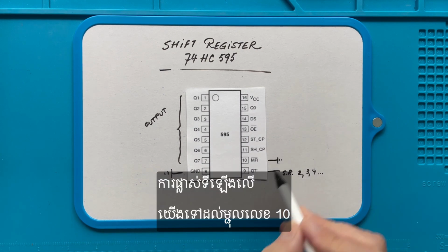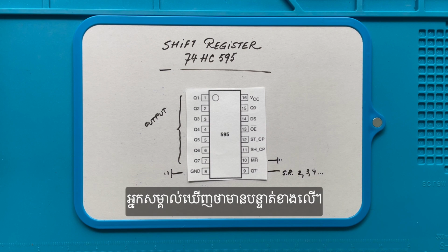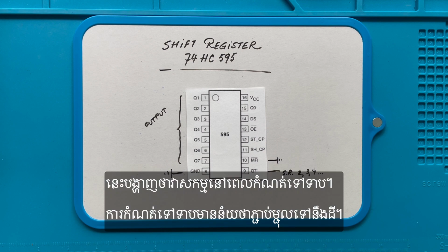Moving up, we arrive at pin 10, which is the master reset or reclear pin. You notice that there is a line above MR. This indicates that it is active when set to low. Setting to low means connecting the pin to the ground.